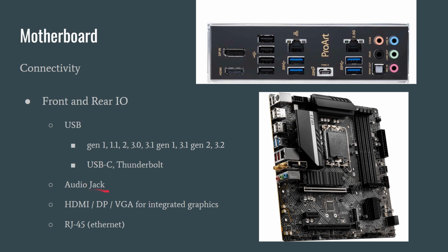And then you have audio jacks, so you probably want at least one audio jack, or maybe you want to support this older version of audio. SPDIF is an older version of audio as well. So just consider what audio you want to do. And then typically if you have integrated graphics, then your rear I/O will support that in some form. You'll have an HDMI port and maybe a display port that your integrated graphics from your CPU can be connected to. So if you want to run a monitor off your integrated graphics, you'd plug it into the rear I/O's display port, not the GPU's connection.